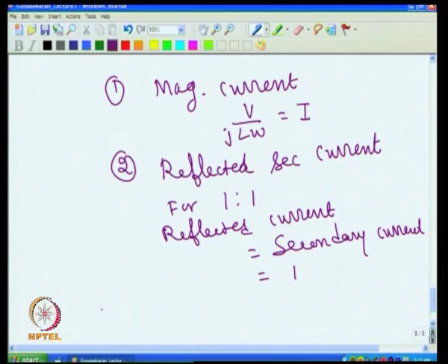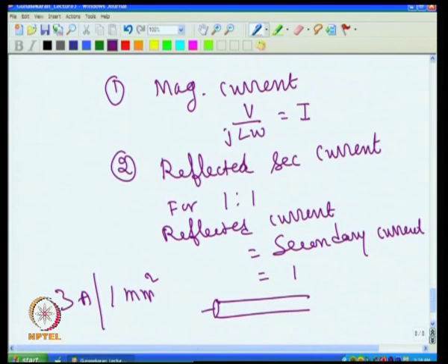Normally, to avoid overheating, we take 3 ampere of current per 1 mm square. That is, if I am winding a wire, we have the cross section of the wire. If this pi r squared is 1 mm square, then I can pass 3 ampere current.